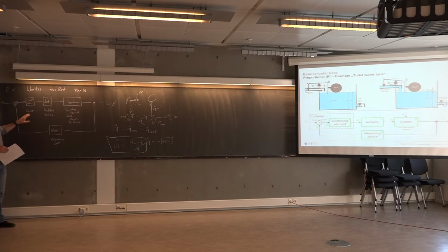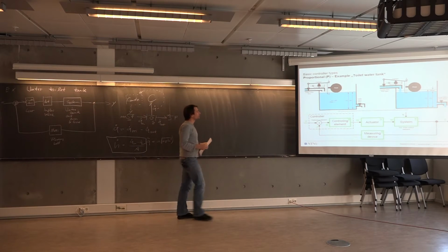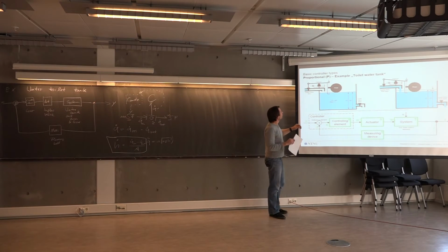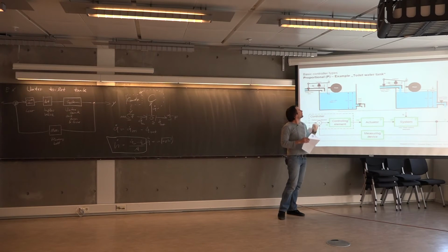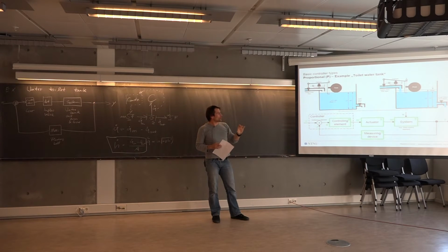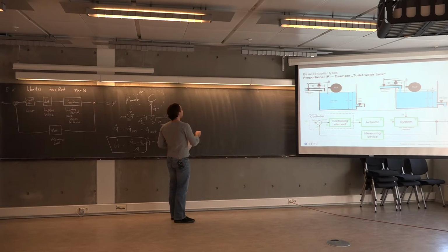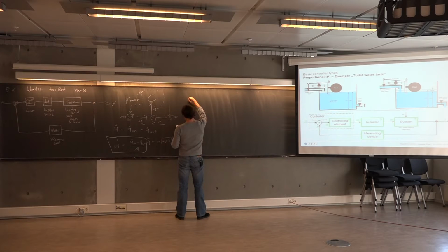Now we need some expression for this control element, some equation, some relationship. Take a look at that lever. It basically translates some change in height or change in water level on the right-hand side to some change in valve opening, the left-hand side of the lever, right? So it is nothing but the linear relationship that we see here.